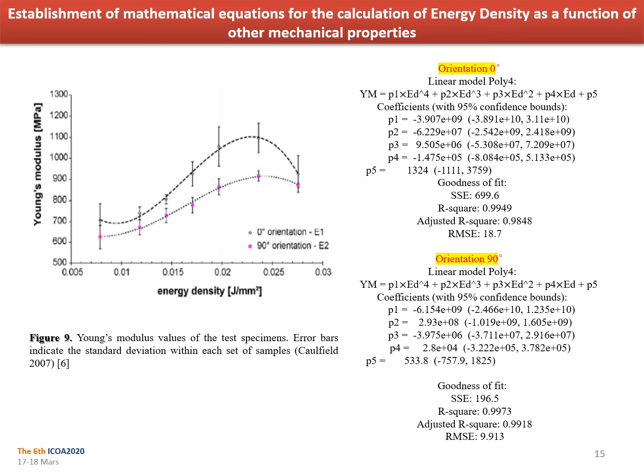The orientation of the parts affects the quality but also the geometric stability. When we talk about orientation, we are referring to a position on the build path, X, Y, and Z. The part can therefore be positioned horizontally, orientation 0 degree, or vertically, orientation 90 degree. The orientation of the parts is one of the important parameters regarding the quality of manufacturing.